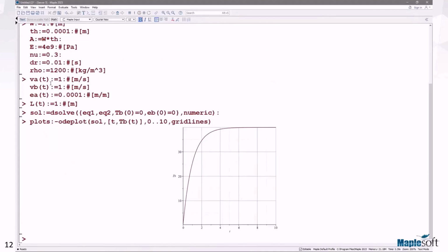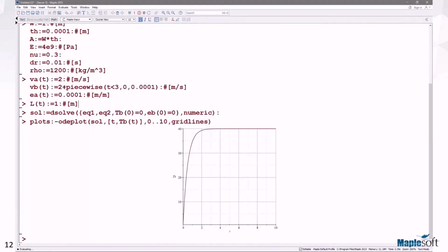We get the familiar curve of gradually reaching the steady state maximum tension, and if we increase the speed of the web, we'll get there sooner. And for example, just like in draw systems, if we increase the outgoing speed midway, we'll have a jump in the tension. But you can imagine if this much work is required for just a single span, if we add rollers and tens of spans and rollers and nip rollers and slippage and all other effects, maintaining it, if not impossible, would be very, very difficult.